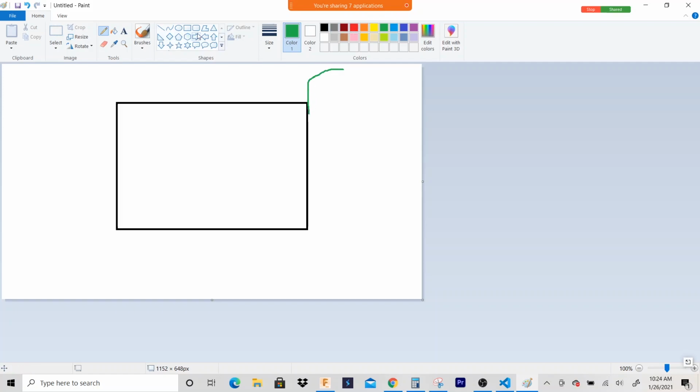Now if you have a circle, there's no circles in here, got an oval. Okay, so you have to think of a G02, G03. Because it has a radial lead-in, you have to think of this as a circle with a center point. So you have to think of your X starting distance. We'll say that this would be a G03. Okay, so we'll just write this.